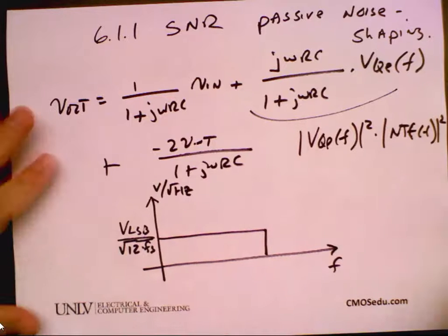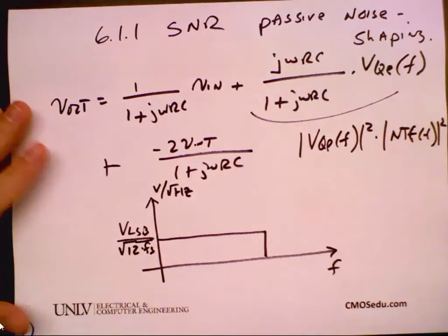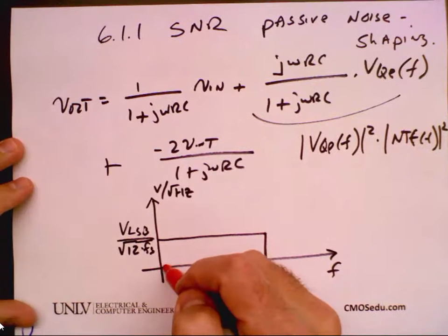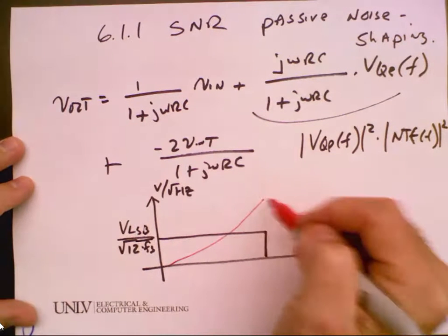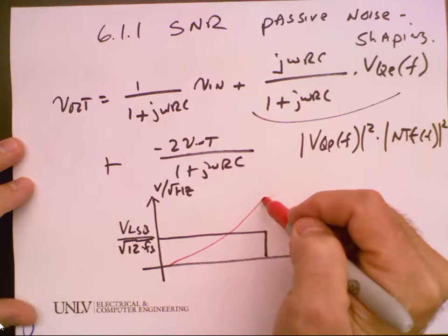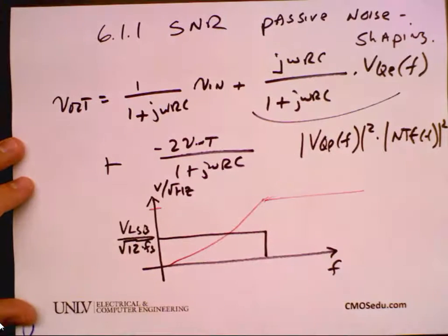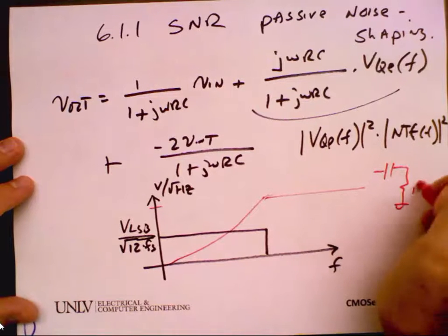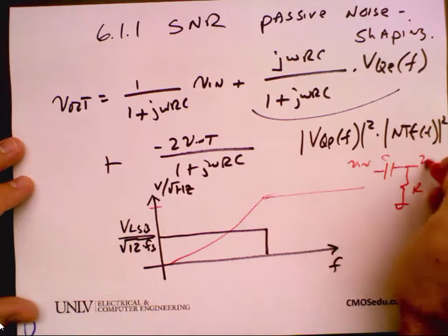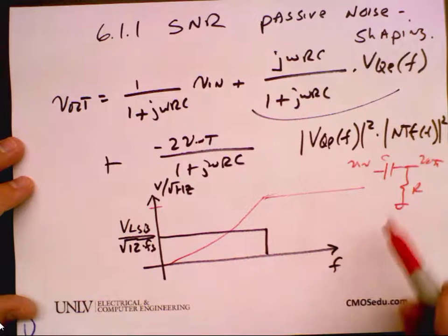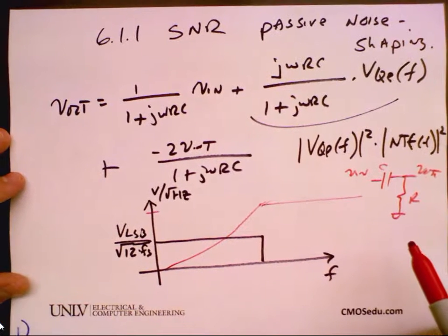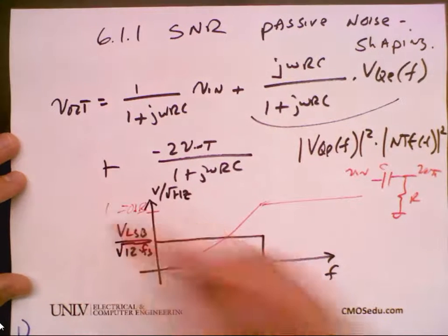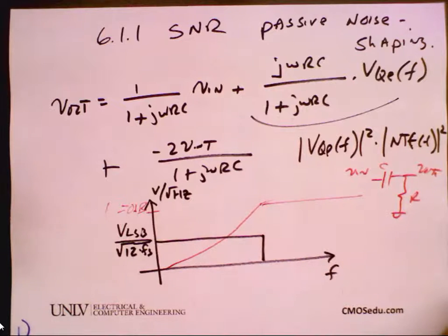Okay, what is the shape of this? It's a high-pass filter, right? It does this. It goes up, and if we keep going, it goes up and then flattens out at what? What does it flatten out at high frequencies? How are V in and V out related? They're equal, so where's this equal to? 0 dB or 1. No questions, right?